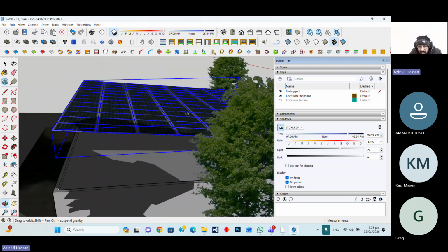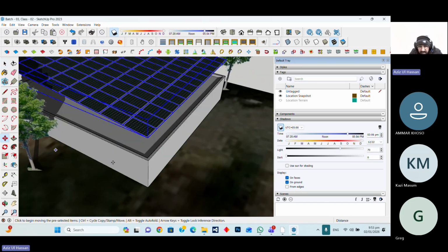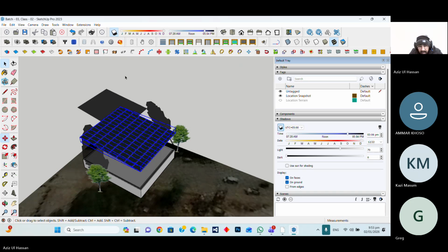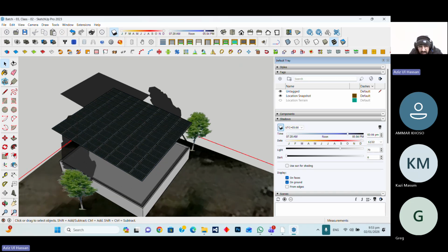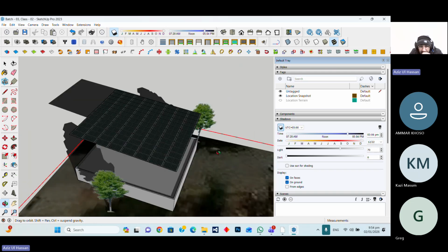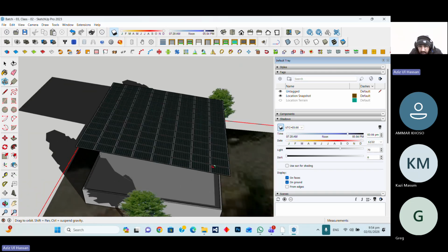So here we have to increase the height. We already gave the tilt angle height as 8 feet. Now we increase it to 14 feet. If we increase the height, our structure cost will increase definitely. But if we have to meet the capacity, we have to do that option. Now you can see that the shadow is not present on the PV modules.